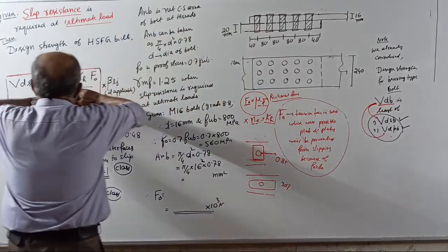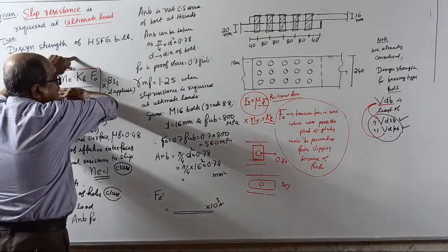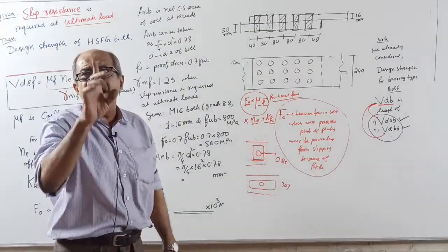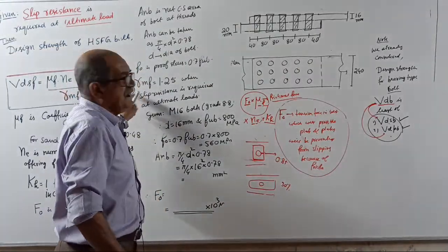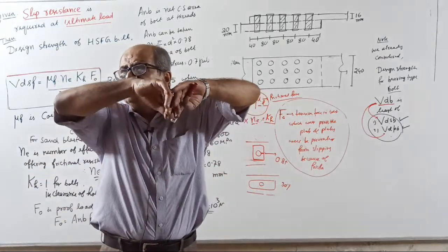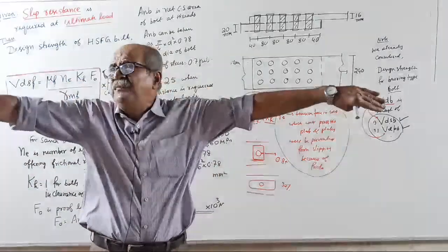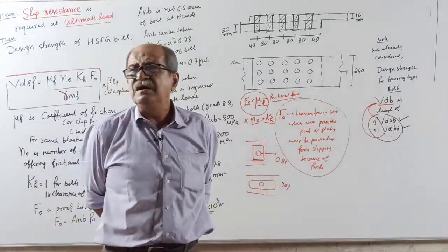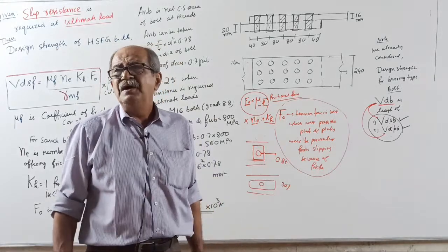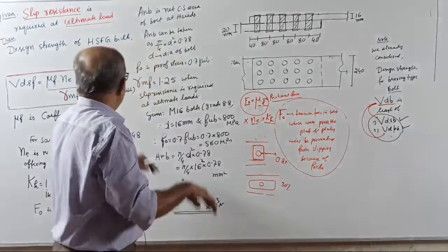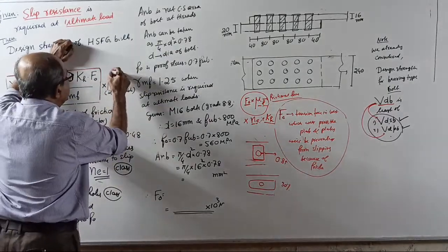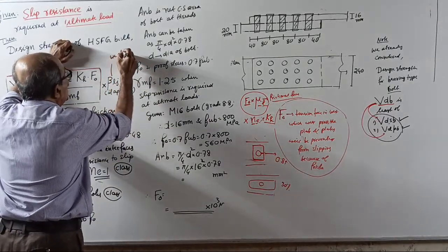So, if I don't use gamma mb, nominal strength by gamma mb. And remember, here also the IS code told a reduction factor to be applied. If the number of bolts in the line of the force is beyond a limit, then the force will not be equally transferred, so it becomes weaker. So into beta Lj, if applicable, beta Lj, we already know.